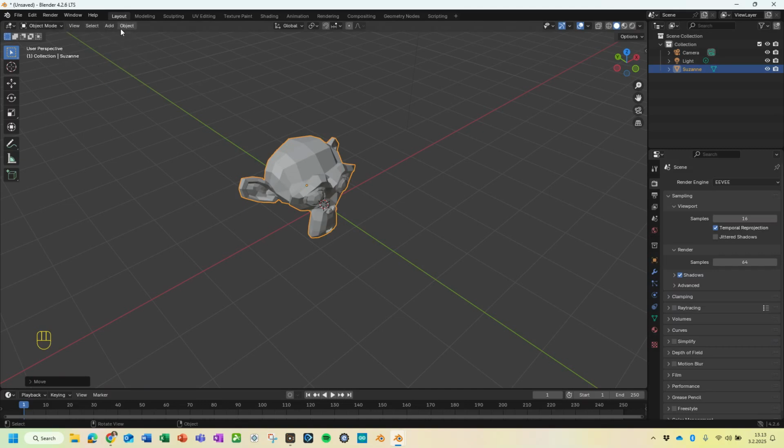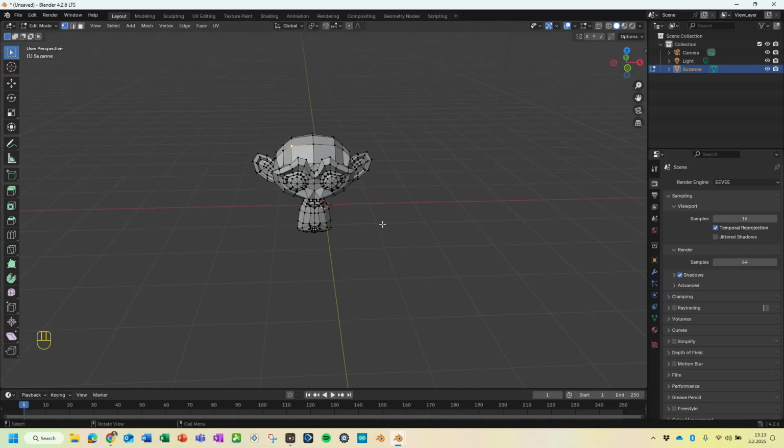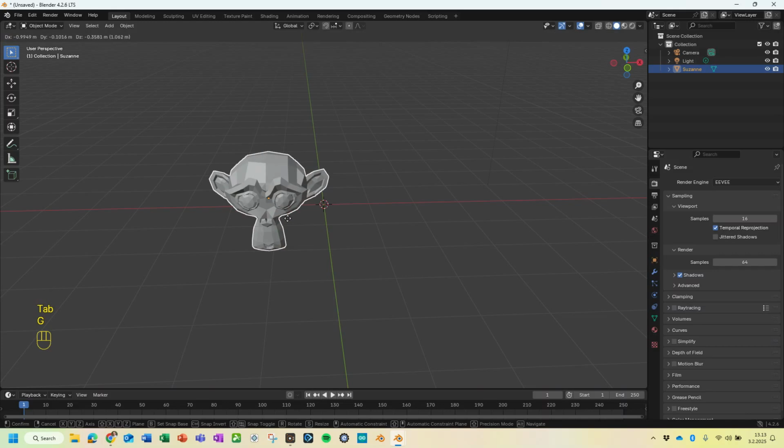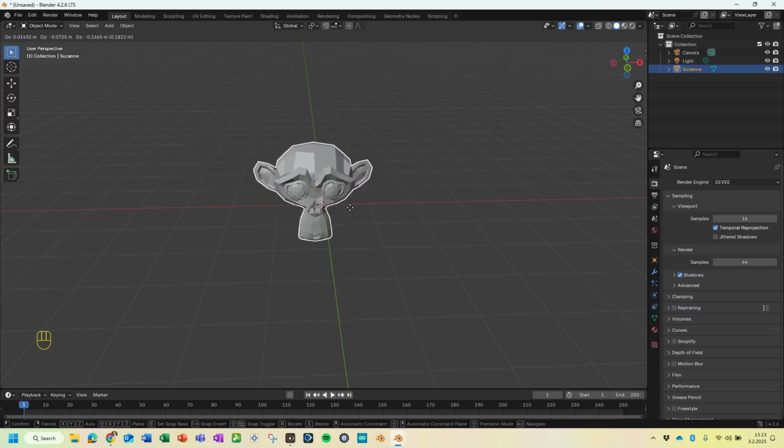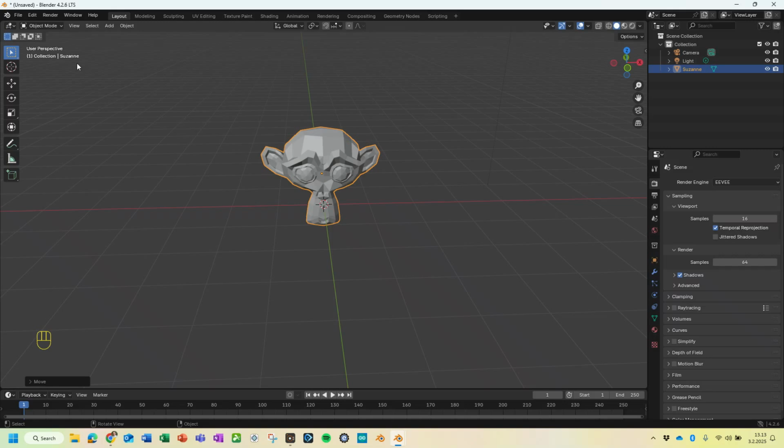Over here you have a secondary menu, and this one actually moves if you change into your edit mode. You can see it's different, or if you go to your object mode, and it's different again. Edit mode means that you can pick any part of your mesh, like you can pick a single vertex and you can move it like so. But when you go into object mode, any moves will apply to the entire mesh. So edit mode and object mode are very important. The others, well, yes, they are important, but not that much.